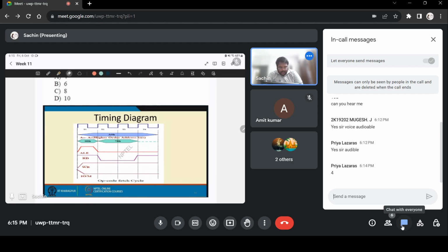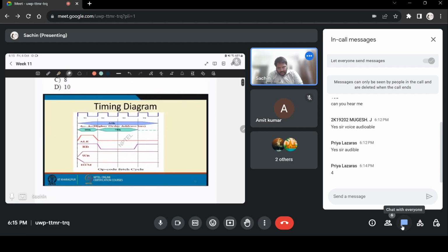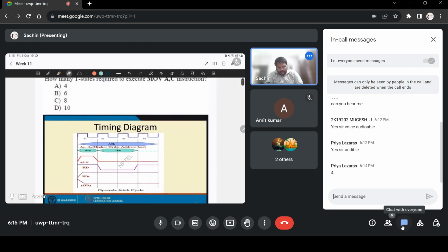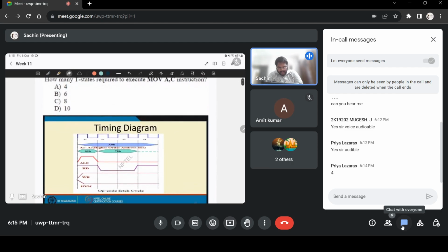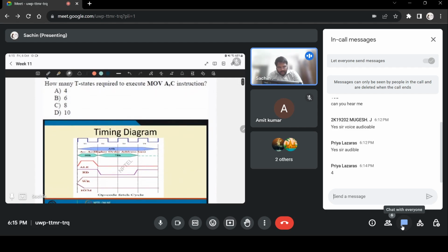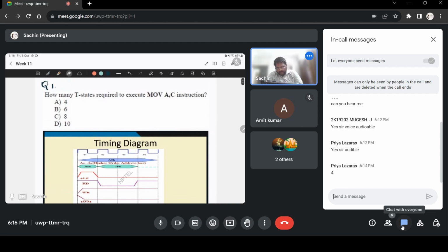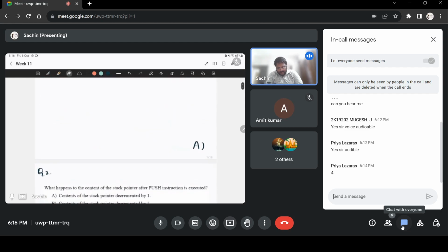And in another clock pulse, the data from the memory will be read by the processor and stored in a temporary register. And then one more clock cycle. Well, we don't exactly know what is happening in the clock cycle, but we could guess that the instruction is being decoded. So 4 clock cycles, that means 4 T states. Okay.